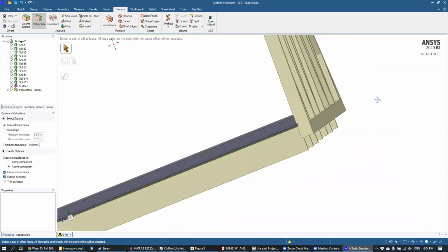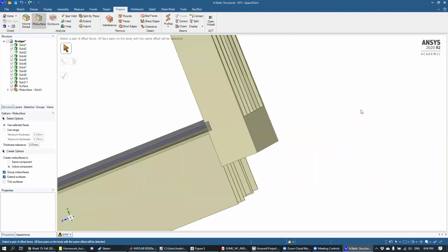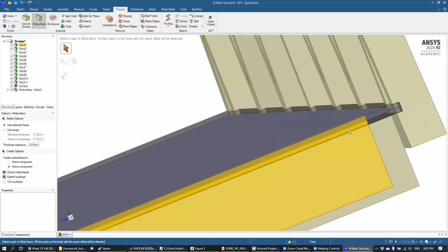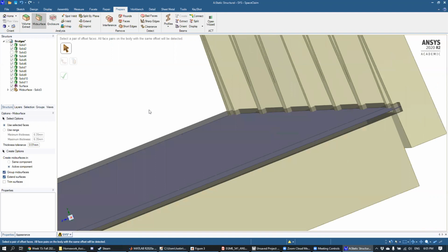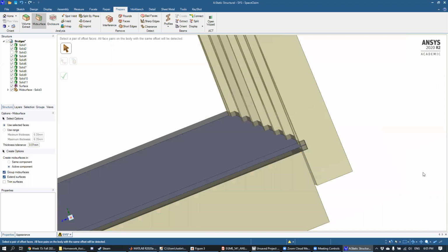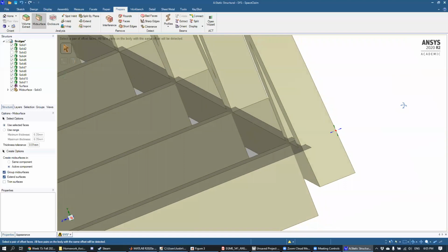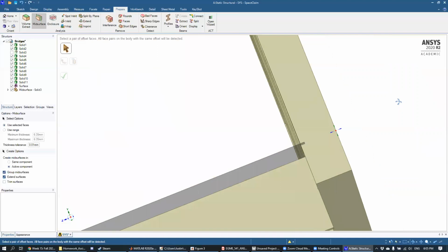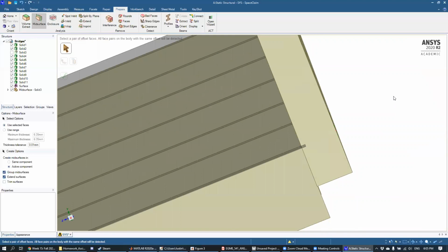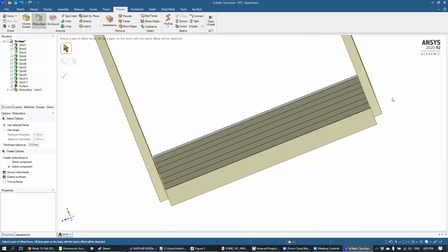You can see here that the original road was grayed out. It's a little bit hard to tell, but the black transparent parts are what the road used to be, and this blue plane in the middle is the midsection that was created. Let's click away, and you can see that instead of our thin road, which had a thickness, we've replaced it with a sheet of paper to represent that road.